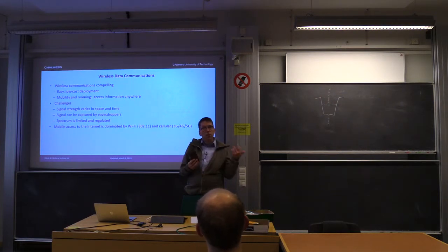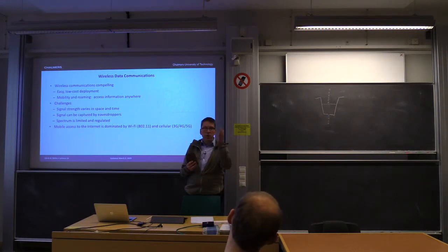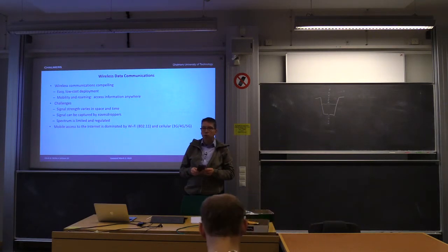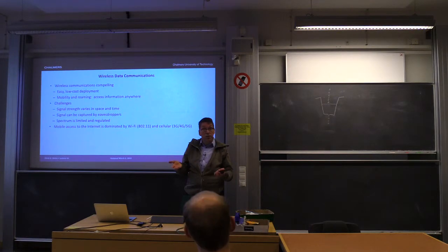And moreover, when there is multipath transmission, where there is maybe a direct path and then a reflection in a wall or something like that, it could create interference patterns where sometimes there is constructive interference between two paths where the signal power actually goes up, but there could also be situations where the interference pattern is such that the signal strength goes down to zero even.